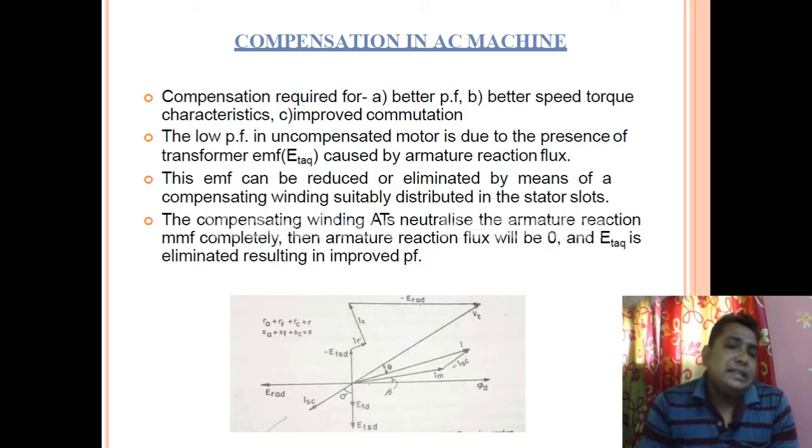The low power factor in an uncompensated motor is due to the presence of the transformer EMF caused by the armature reaction flux.